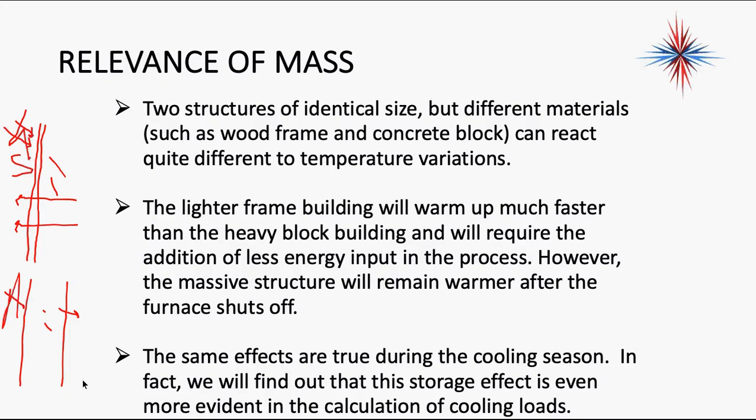Okay, and when we deal with cooling loads, we have to take that into account, especially with commercial buildings. Okay, now some of you, if you live in an older farmhouse or a brick building that has stone or brick around 2 sides of the house that get direct sun, you may see this, that one side of your house may remain warm way after the sun goes down. Okay, sometimes in the winter months we can use that to our advantage, but in the summer months that becomes a problem. Any questions on this? Because this is sort of important as we're looking at heat load.